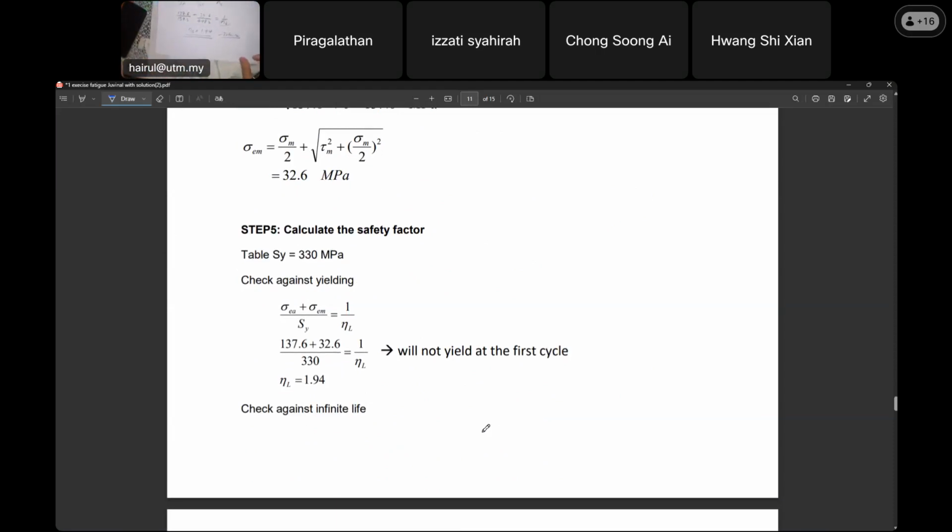Clear tak kelas? That's how you do fatigue: you find the fatigue safety factor based on fatigue analysis of the shaft. Why the formula is like that, I will explain next class meeting; there is a reason at the plot of the graph. I showed you one example of how to calculate fatigue analysis on a shaft. This is a simple problem because the shaft is plain. Another example next meeting is a stepped shaft with a shoulder and stress concentration factor.